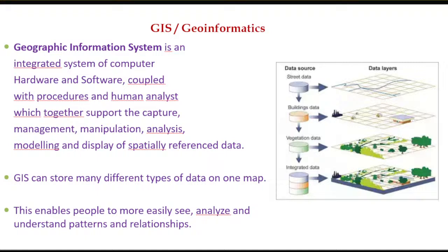So both have information, but in different formats. The representation here is a raster format, and there it is a vector format. Raster format means image format. We are depicting the information in the form of an image, made of pixels or pixel elements, or sometimes dots per inch, whatever it is. All the pixels will have a DN value, and the DN value will vary from 0 to 255. But here it is a CAD kind of diagram, where you have an XY location for each and every point. So this is how you define the spatial data.